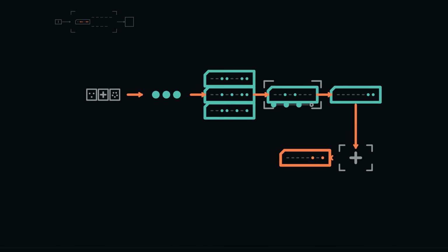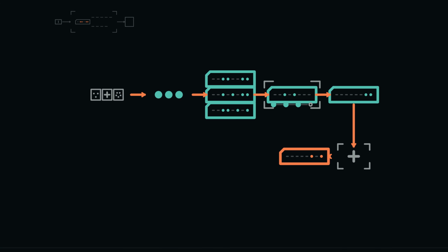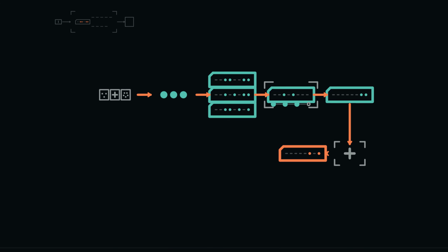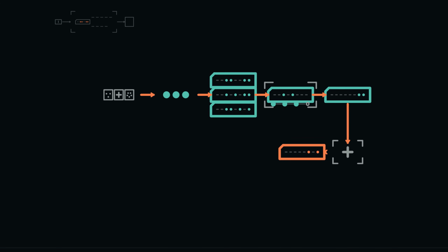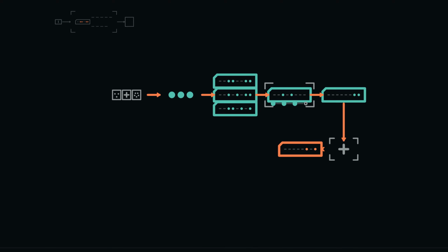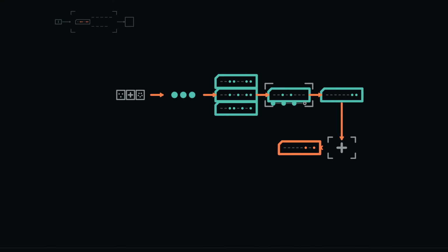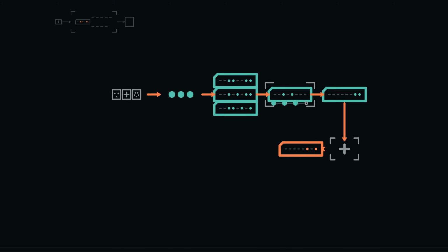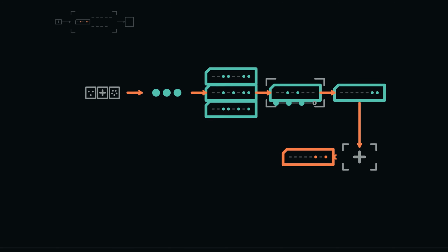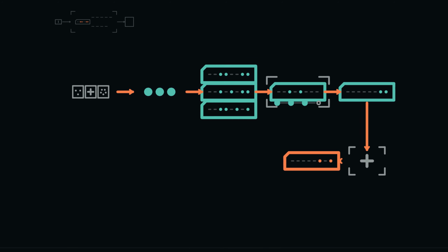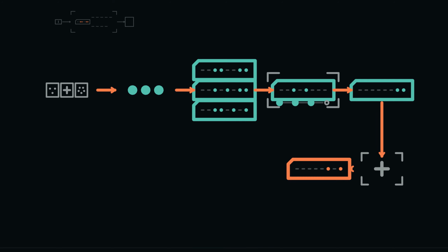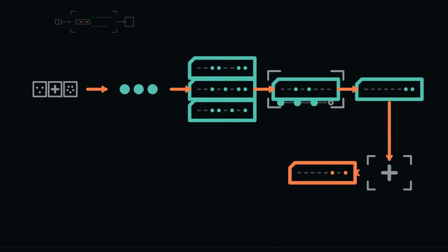The third data load consumes hexadecimal 35 into R1. Subtracting the digit offset produces numeric 5. Now the addition instruction routes R0 and R1 to the arithmetic unit. The first entered digit supplies 3, the second entered digit supplies 5. The validated operator has selected addition. The carry-linked adder therefore computes 3 plus 5, and R0 captures numeric 8. The result has 2 operands and 1 operator. No input has been omitted or replaced by a hidden constant.